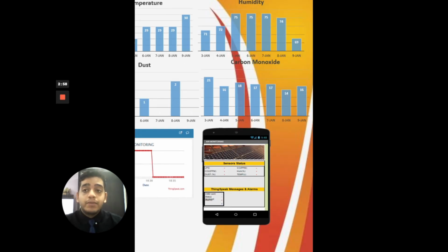Finally, the carbon monoxide graph, obtained from the MQ7 sensor. There are readings that will indicate whether the level of carbon monoxide gas is safe or harmful. For example, 50 ppm and below is considered a low level or safe. When the reading reaches between 51 ppm to 100 ppm, it is considered medium condition. If the level of carbon monoxide gas exceeds 100 ppm, then the air is considered harmful or not safe.